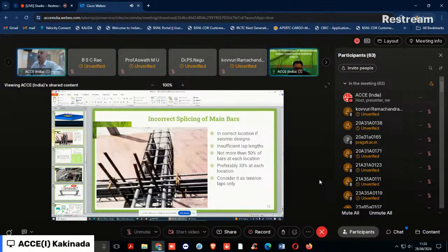When you are using a non-seismic resistant design, like in the previous cases, the ideal location is at the top of the slab concrete. That is the location where the flexural yielding plane in the column is at the middle of the section. Suppose it is taken as a fixed end column as a boundary condition. 0.5 L is the effective length and the midpoint is the yielding point.